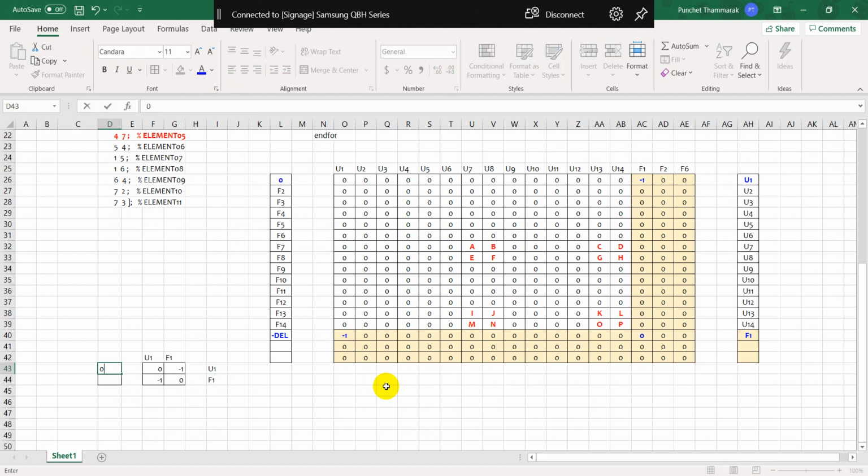It's going to zero this one. If there is anything, it is going to be 0 first, because it will be replaced by the F1 over here. This is minus delta displacement. Over here we prescribe it to be 0, but I just generalize it. Zero this out, put the minus delta in here, put the minus 1 in the row associated with F1